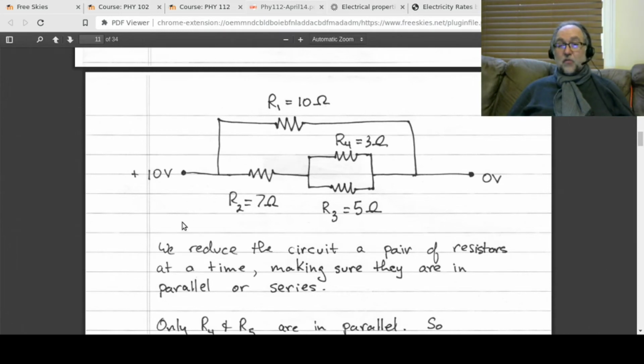So this is a different way to draw a circuit. You say, well, I don't see the battery. I know. Sometimes circuits get a little bit complicated, and so rather than drawing a whole bunch of things, you could imagine that there was a battery attached across here, and this battery is applying 10 volts here, and there's your 0. So this is like the positive side of the battery at 10 volts, and here's the negative at 0 volts or ground. Okay, 0 volts is sometimes called ground.